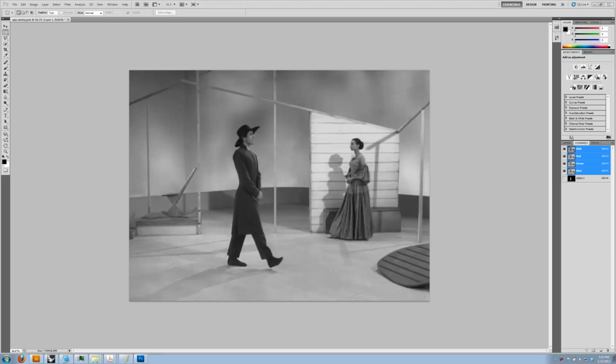What I'm going to talk about is basically a few things. How to get a scale figure out of Photoshop and into a vector program like AutoCAD or Illustrator or Rhino, which might be of interest. And then for most of the video I'm going to talk about how to extract 2D lines from any view in Rhinoceros and get them into a program like Illustrator or AutoCAD. We do this for this assignment so that we can construct orthographic drawings of our three-dimensional forms. Okay, so to start with, I'm going to talk about the scale figure.